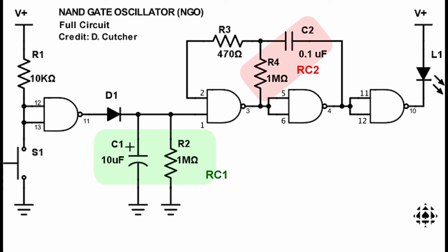of low at pin 4, and then pin 4 would input 2 low signals at both pins 11 and 12, which would output a signal of high, which would not allow the LED to turn on as it has no path to ground. The difference in charge between pins 3 and 4 also charges the capacitor in C2.